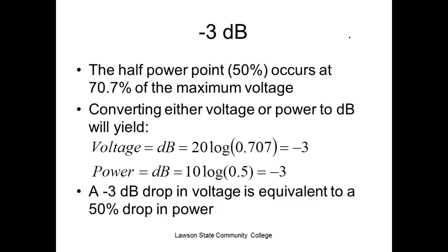Minus 3 dB. So you'll see a lot of people talk about the cutoff frequencies, and they'll say at minus 3 dB. And of course, what are they talking about? Are they talking about voltage or are they talking about power? They're talking about both of them. It's just if I measured my voltage it would be 70.7%, which gives me a minus 3 dB power loss, right? Okay, so this is the way they do it.